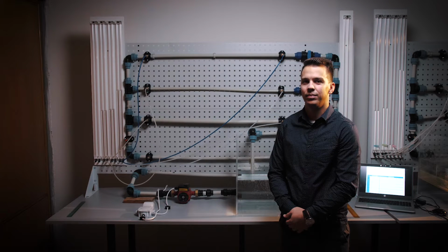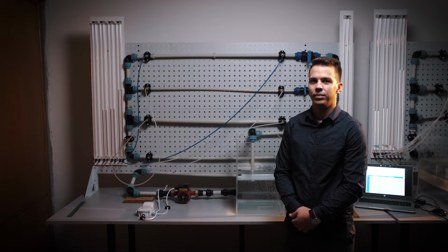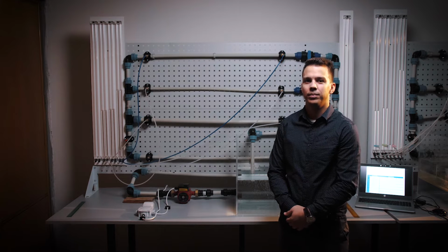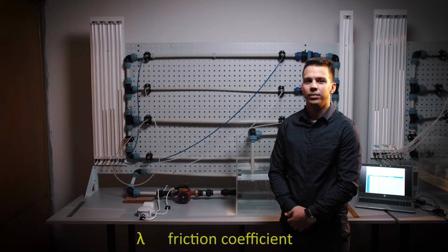In this measurement, we will deal with the loss of fluid energy due to internal friction. As we already know, the cause of it is viscosity. In the case of turbulent flow, the roughness of the inner wall of the pipe also contributes to the losses. Our task will be to determine the coefficient of friction lambda and to compare the obtained values with theoretical assumptions.